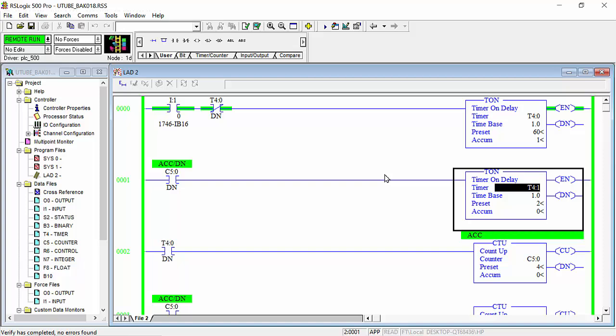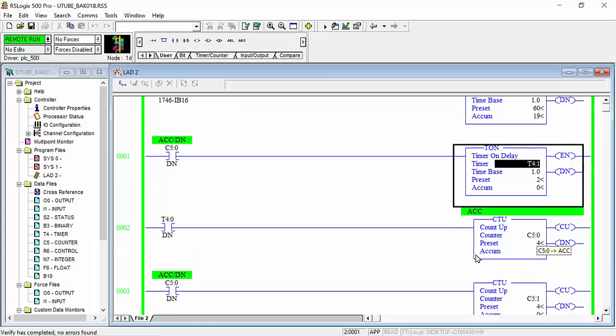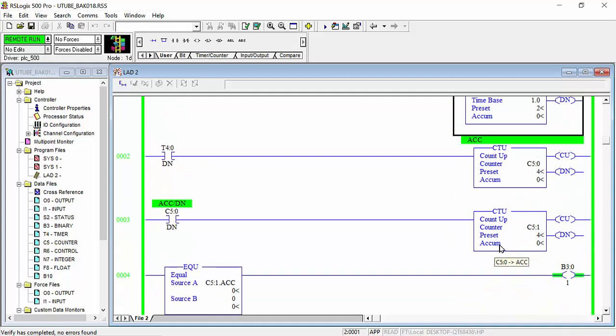See, when I give the signal I:1.0, that first bit, when I turn it on, my timer is now started. But this is a very long timer, because we decided 60 seconds, after 1 minute is completed. And here this counter also we decide 4, when this is completed for 4 minutes, after this will be completed. This is our time for this release.